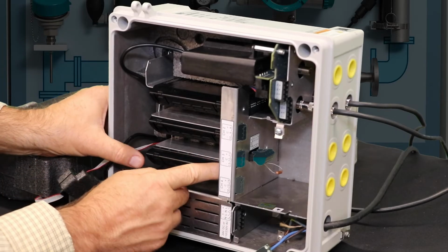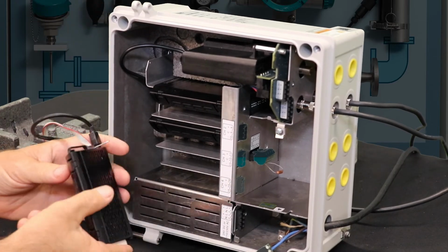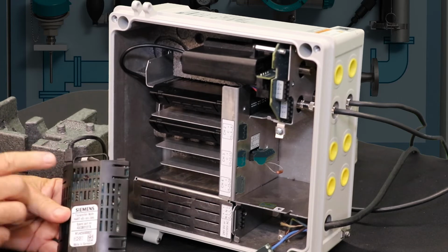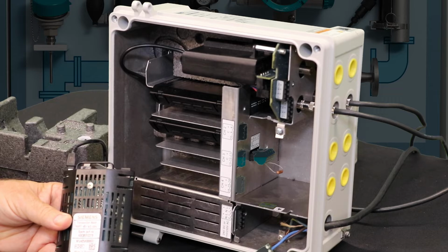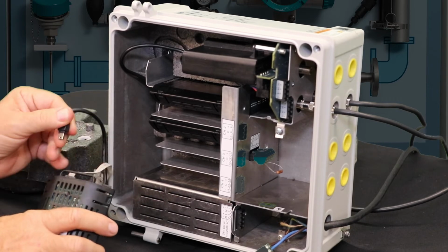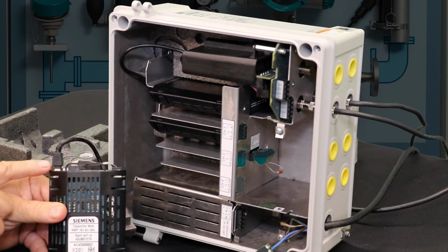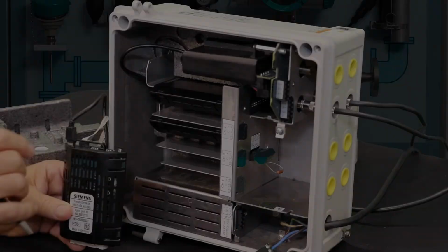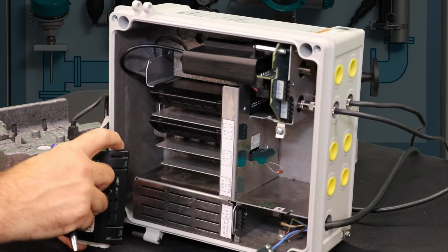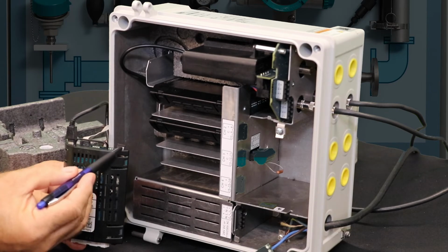One other thing to mention is if you're trying to communicate with the meter using the service port via either FS230 tool or PDM, and you're not establishing a connection, you may want to reset this small extension cable, because on occasion it has known to come loose. And I'll also point out that the SD card plugs into this slot up at the top.